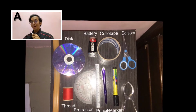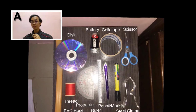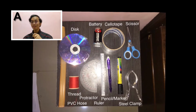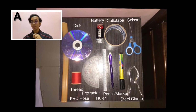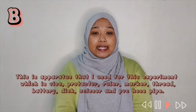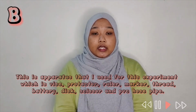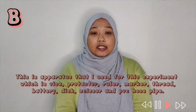For section A, I use a 0.4513 Newton battery as load, PVC hose as the tested material, a disc for radius measurement, thread for transferring load, a protractor, a ruler, a pencil, a marker pen, a steel clamp, a scissor, and sellotape. This is the apparatus that I use for this experiment, which is vise, protractor, ruler, marker, thread, battery, disc, scissor, and